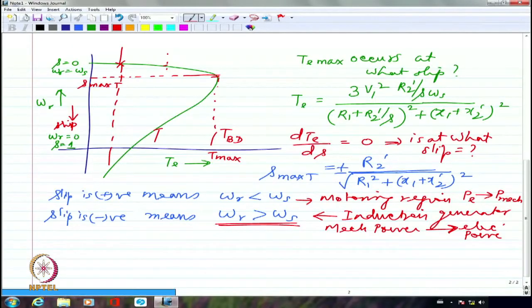If I have a constant torque load, for example, let us say I am talking about an elevator. Elevator is driven by an induction motor, let us say. So 8 of us have gotten in. Maybe the torque corresponds to some value like this. It is starting from 0 speed, clearly. So unless I have some amount of torque in excess, there is no way acceleration will take place.